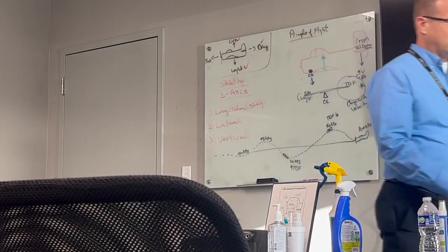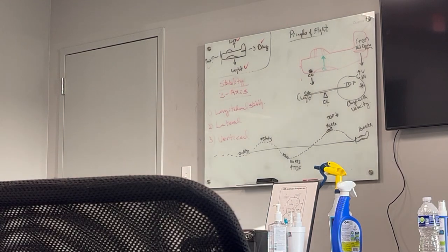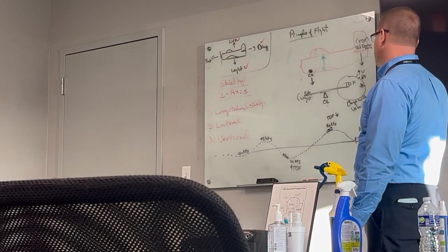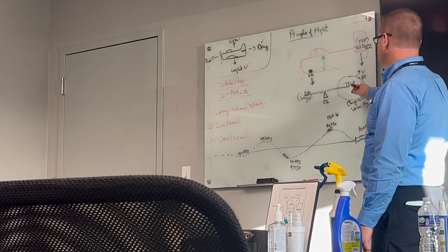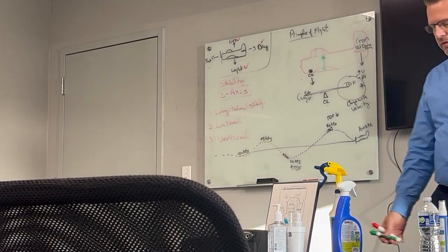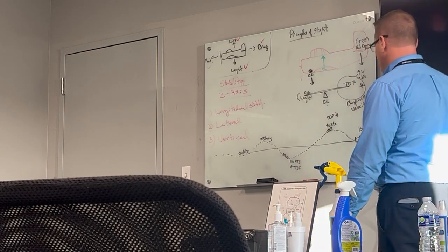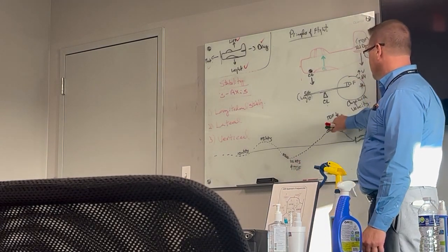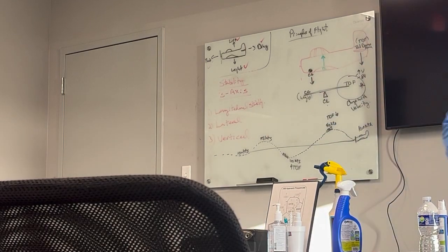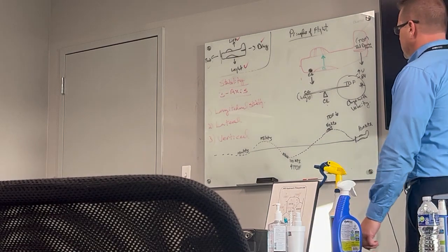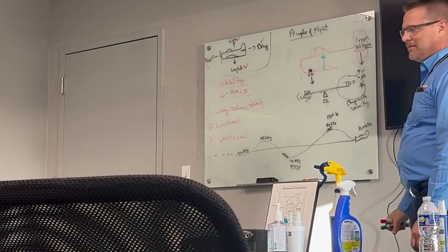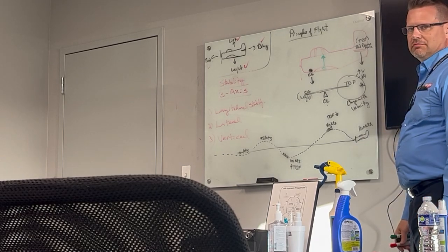Just like the positive dynamic line graph chart, same thing. And it all has to do with tail down force. It has to do with the fact that it's an upside down wing, and the force varies directly with velocity, just like our wing. The faster we fly, the more tail down force; the slower it flies, the less tail down force, and that's what keeps it having that positive dynamic stability. That's the hardest one. If you can explain that, you've pretty much got stability, because the other two are simple.